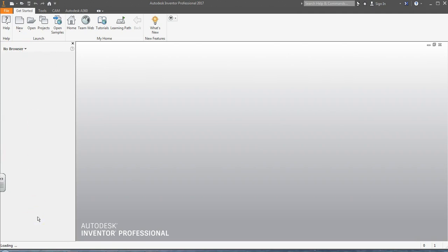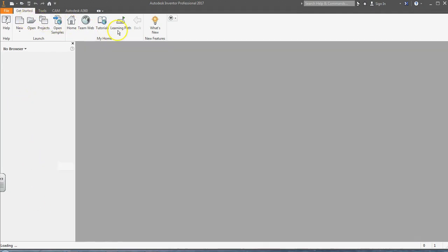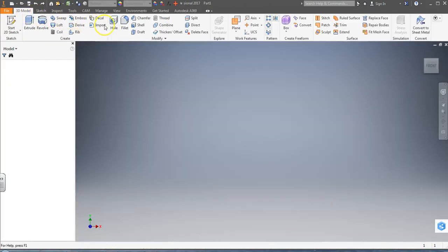And we're still loading. So while it's still loading, let's talk about this tool ribbon across the top here. These are the different things that I could have. There we go, there's the rest of the ribbon. 3D modeling, sketch, inspect, tools, CAM. This is for if we have Inventor HSM loaded, or CAM software, so we can put a tool path to our part and program it for the CNC machines, which we will do in a later video. And all these things fit within the different choices.